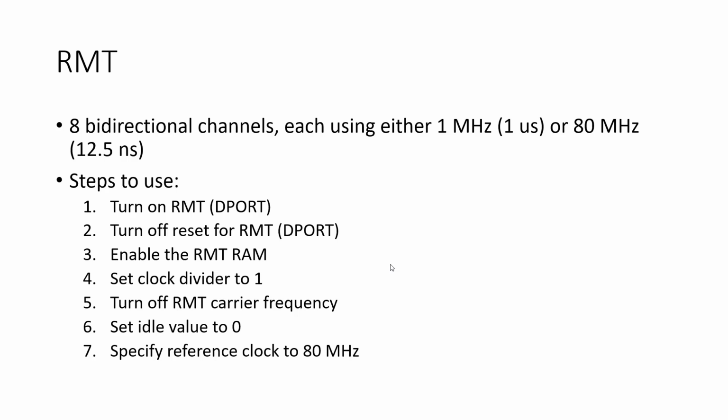So why exactly, right? And by the way, Alex, this nearly drove Alex insane, this step, because 5 hours. My writes wouldn't stick. I finally figured out you have to turn on the stupid RAM. Remember I mentioned that I read all my writes back to confirm they wrote? Alex doesn't do that, and as a result, he wasted 5 hours. I was reading them back when I was doing this, trying to figure out why they weren't sticking. I looked all over the data sheet, and I finally found it. So he was writing, but it wasn't taking effect. And it turned out that he had to enable the RAM to make them take effect.